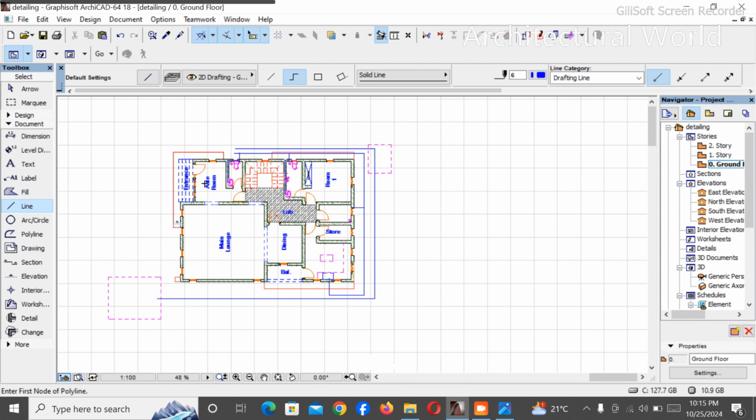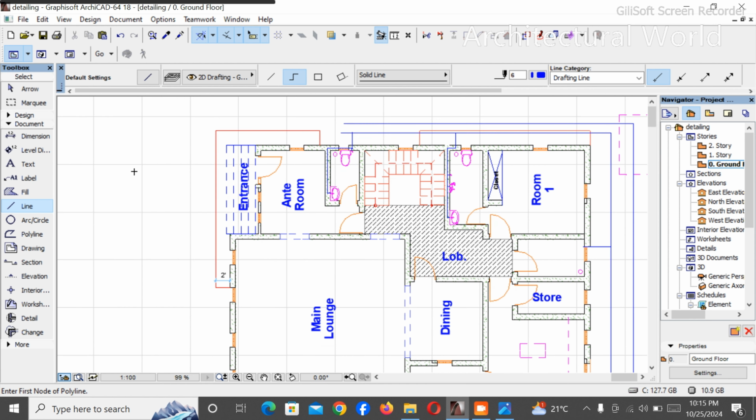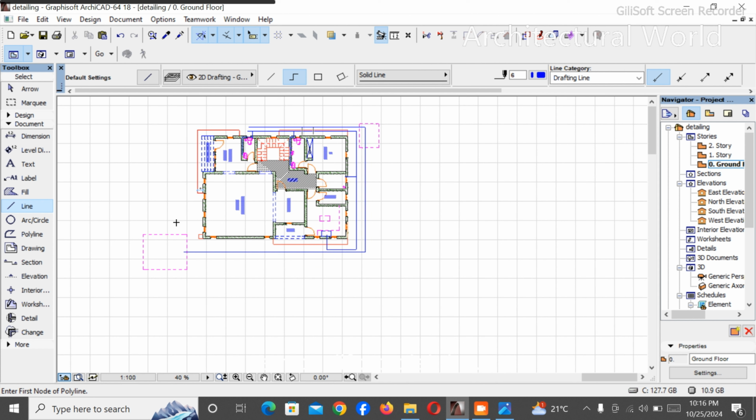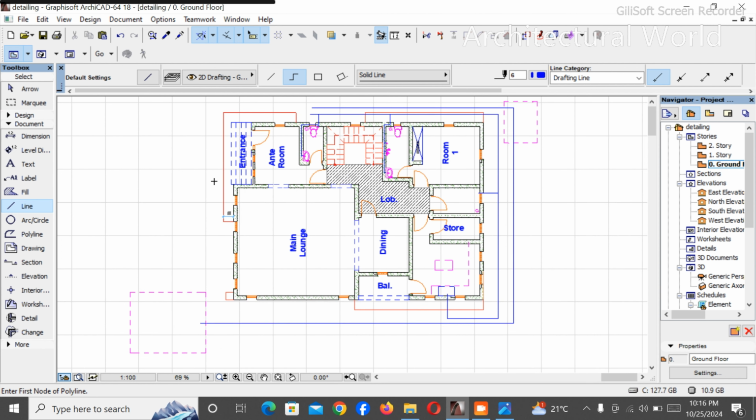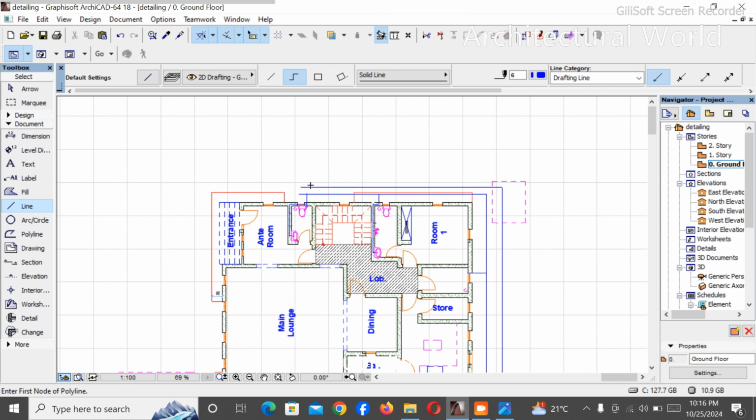So you are supposed to run this. The shortest distance for this connection, in case you want to do it, is through this process. You can bring it from here, pass through the front of the house down to this part. Then you bring this from here and down to this part. That is the shortest distance, but that is the improper distance because you'll be needing chambers at the front. You're only advised to use this method if you are working a chamberless design. But if you are not doing a chamberless design, you will be needing chambers for all these things.